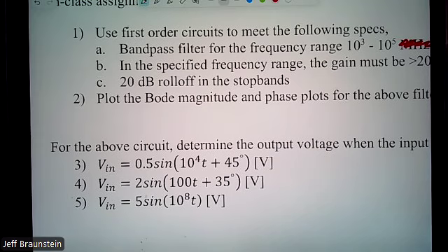You said the op-amp obviously has no current going to it. Do they introduce extra current into it? Why does that happen? This is a whole conversation we'll do in electronics, but the input circuit for the op-amp is what's called a high impedance input. High impedance just means really big resistor.